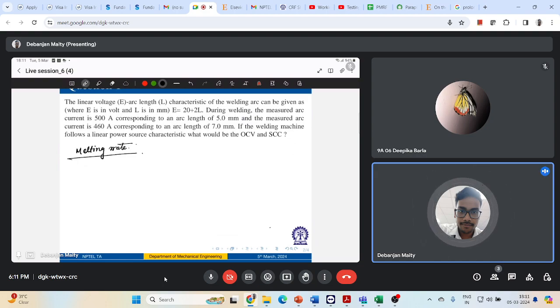If you apply a welding current, supplied through your electrode and through the arc to the workpiece, the flow of electricity results in electrical resistance heating of the electrode, which affects your electrode melting rate.